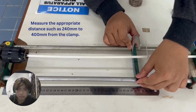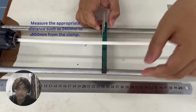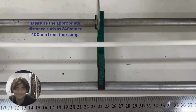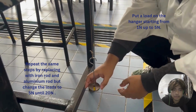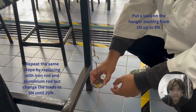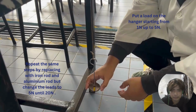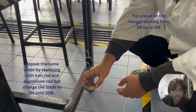Next, measure the appropriate distance such as 240 mm to 400 mm from the clamp. Next, the pointer was fixed at 0 before starting to collect the data. Next, put a load on the hanger starting from 1 Newton up to 5 Newton. And lastly, repeat the same steps by replacing with steel rod and aluminum rod, but change the load to 5 Newton until 20 Newton.